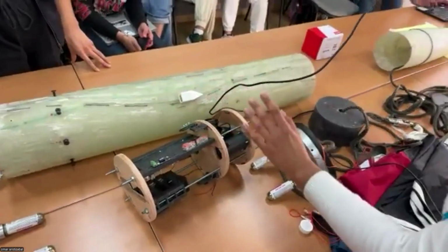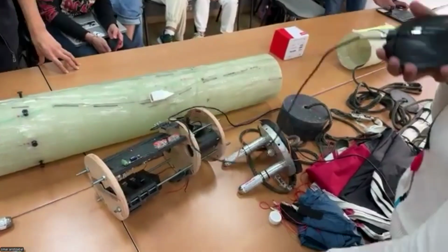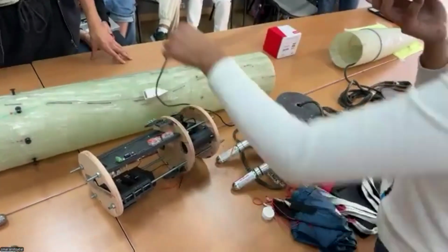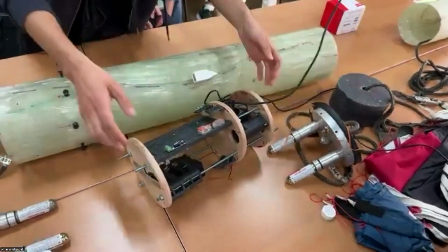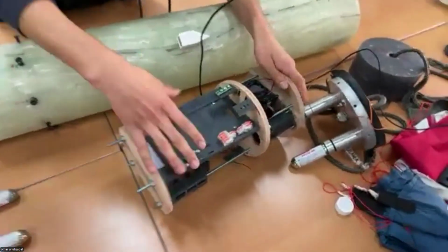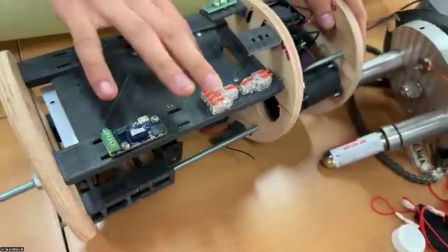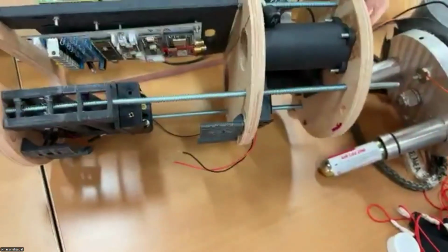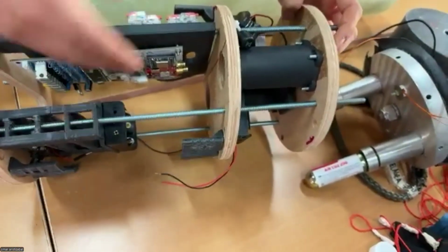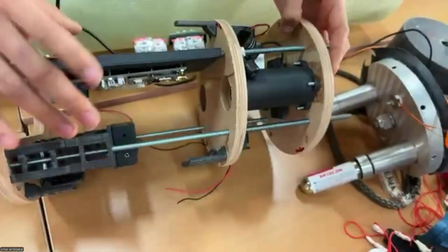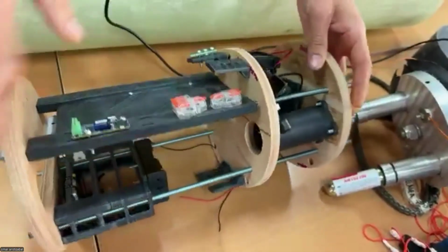They are 0.2 inches. There are 4 of them around this fuselage for the static ports. Also, you can see that the COTS computers are on the other side. They're opposite to the CO2 cartridges, as those freeze when they activate. So they're on the other side, so they don't mess with the barometer readings or anything with the COTS computers.